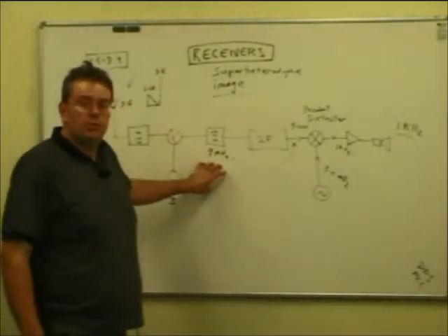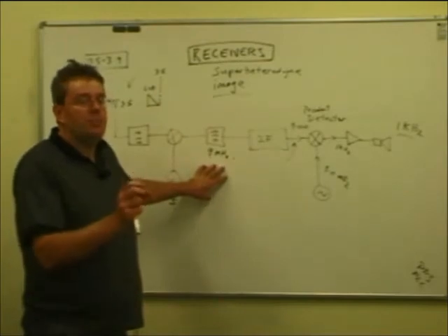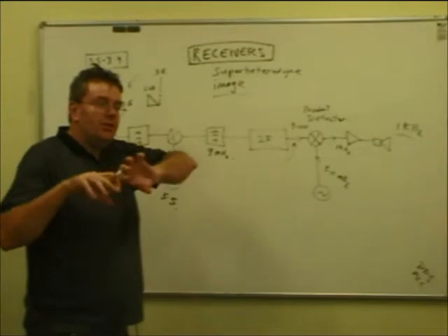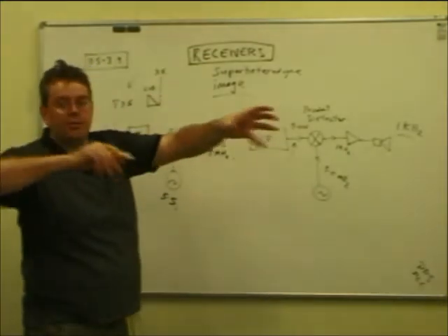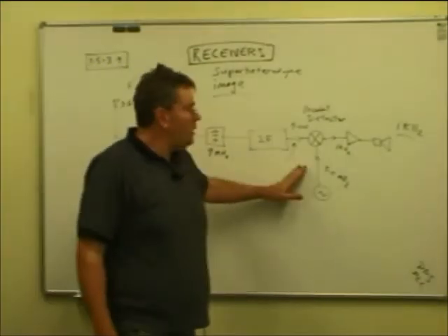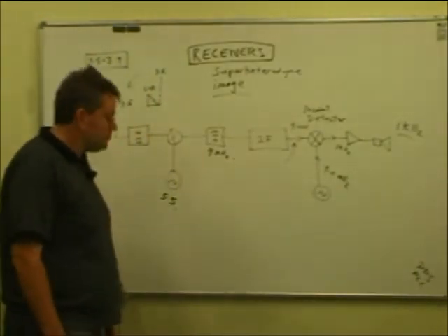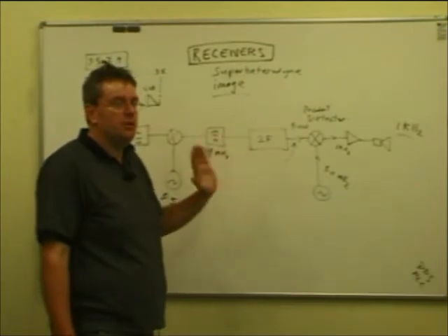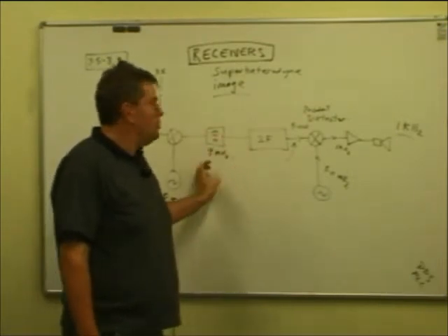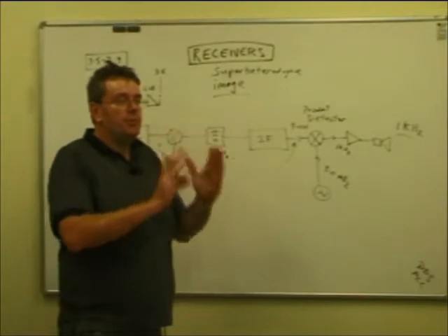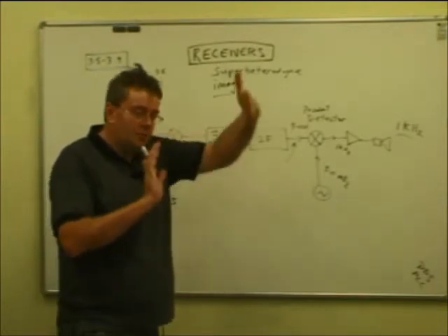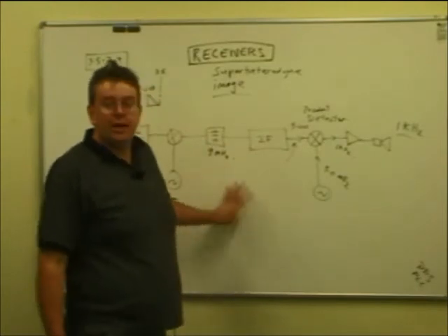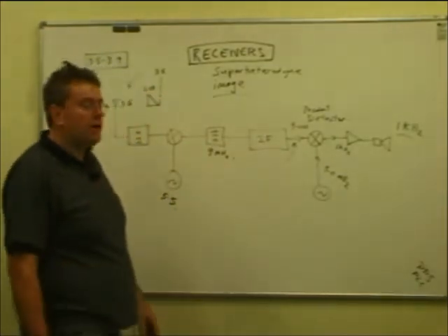Because if we make the filter too wide, what will happen is when we tune to a single sideband signal we want to listen to, if we've got a wide AM filter in there, we might hear the SSB conversation a few kilohertz up get through. So we'll hear two lots, which is a pain. We don't want that. Likewise with Morse code, we've just got one carrier signal for all intents and purposes switching on and off. We can actually use quite a narrow filter in there, because with Morse code you can stack a lot more Morse conversations up the band quite closely together, and so it's an advantage to use a narrower filter for Morse code requirements.